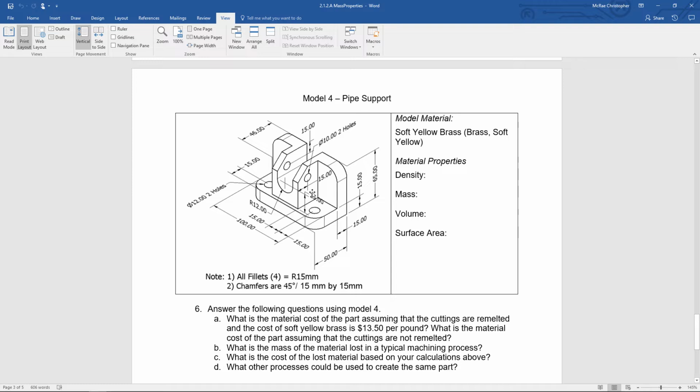Okay, we can tell that this surface to this surface is 30 millimeters because we have some distances here, 15 and 15, that's 30, and it's the same on the other side. And we know that, so let's just go ahead and make those. We also know that this flange in the back is 15 millimeters thick, and we see that by this dimension. So let's go to Inventor.